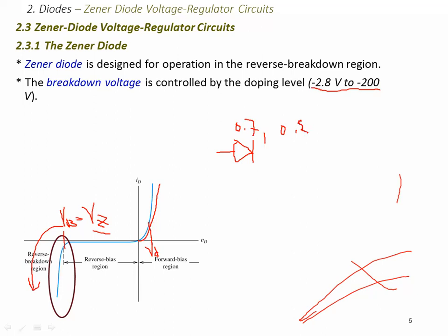Once you reach that voltage, it starts conducting continuously and tends to maintain that voltage as long as it's in forward bias. The Zener diode will get into breakdown when it reaches breakdown voltage, which can be in this range depending on the doping. Then it will maintain that voltage while the current will be increasing across it. That's the characteristic of our Zener diode.